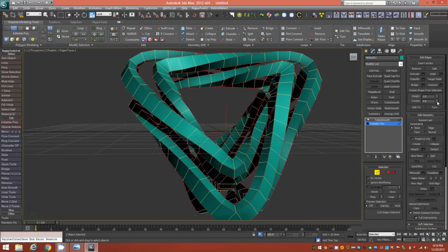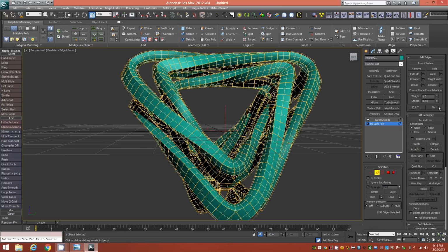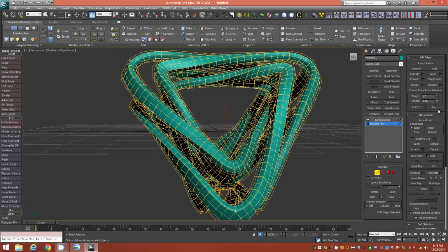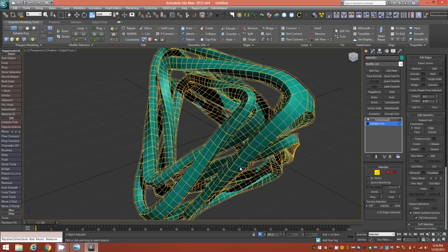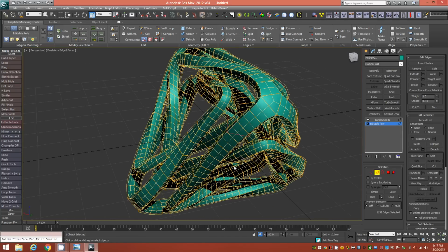So now I'll just increase the crease parameters under the edit edge option, and I could go and look at the end result, and just judge where I want to crease that. Again, this is not as clean a crease as the newer algorithms are, but it works fine for 3D printing, stuff like that.